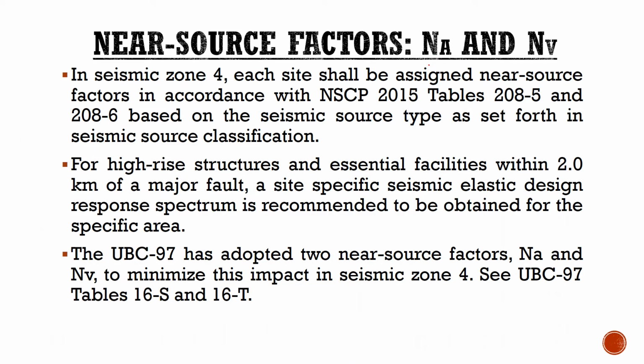In seismic zone 4, and Davao City is in seismic zone 4, each site shall be assigned near source factors in accordance with NSCP 2015 Tables 208-5 and 208-6, based on the seismic source type as set forth in the seismic source classification.